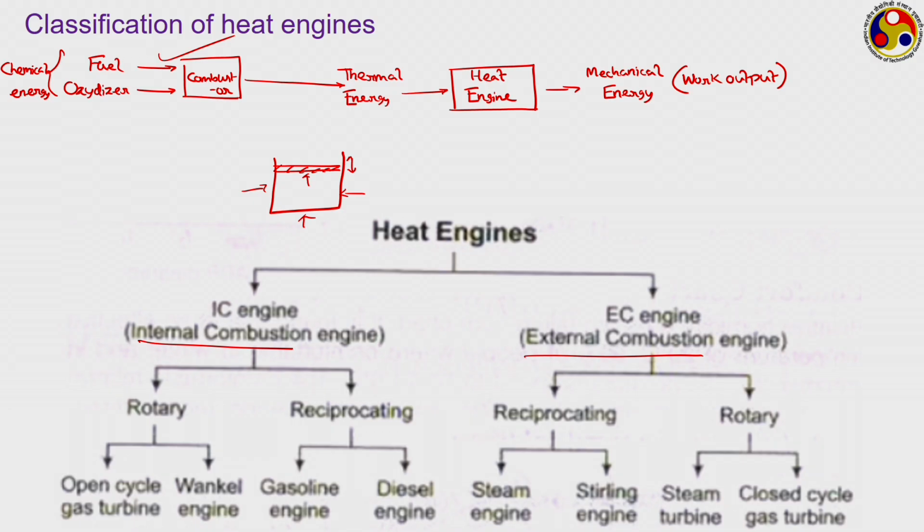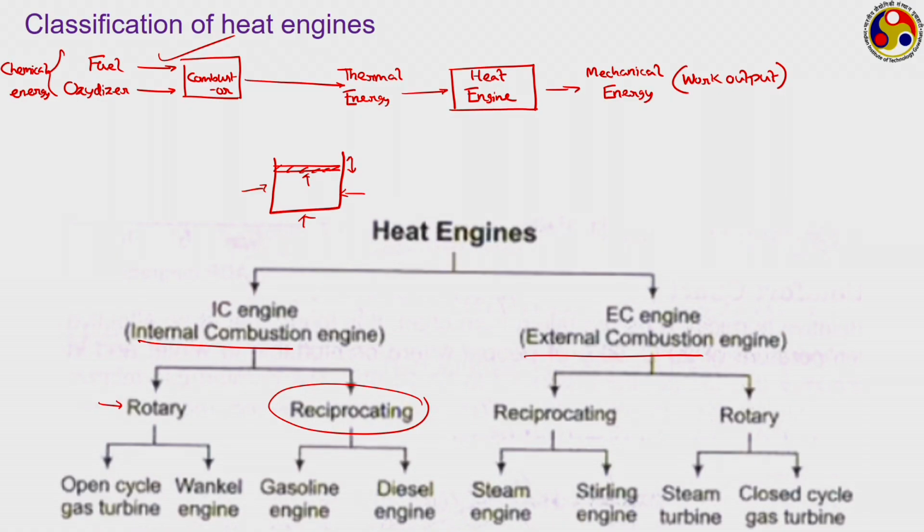Whereas in case of a rotary engine, it is not one, rather it is a combination of multiple devices. So, reciprocating engines primarily correspond to some kind of closed system, which of course allows the supply of fuel and air and also the exhaust of burned gases during some part of the operation, but during other parts it acts like a closed system. Whereas rotary kinds of engines are a combination of multiple systems or multiple components. Each component does one specific job, and the output of that is taken to the subsequent one.